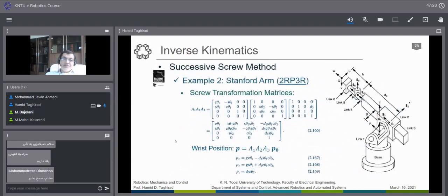First of all, we can use a physical intuition that this P point, the radius or the difference from the P point to this A point really doesn't matter to the theta angle, and also doesn't matter to the other theta 1 and theta 2. This means that if we just square this equation and sum them up, Px squared plus Py squared plus Pz squared, we have cosine and sine squared here, and also here, and then simplify that.